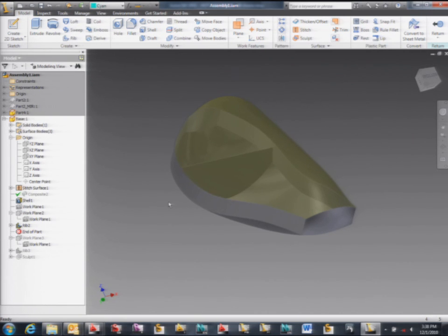So that rib, I can do it in AutoCAD. Of course I can do it in AutoCAD. I will just get the surface, make a projection like we learned. So I get a spline on the surface, then I'll get a spline on top of that. I make a loft between both and make a thicken. Inventor has something called rib that makes ribs, right? So if you just draw a line where you want the rib, Inventor will calculate exactly what's the size of that and how to top it. In AutoCAD, you will be doing operations and operations and operations to get that. Okay, can you do it? Yes. Does it make sense? Probably not if you have a digital prototyping application like Inventor next to it.